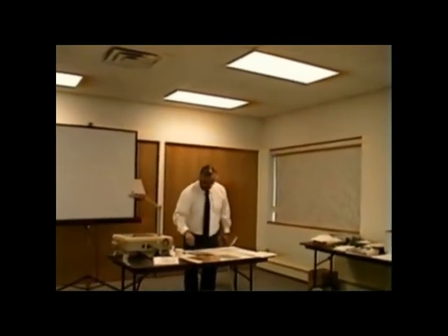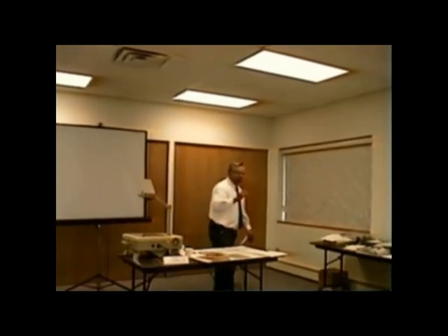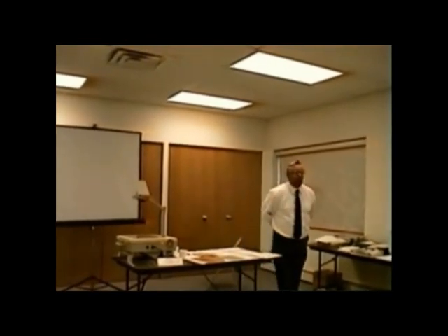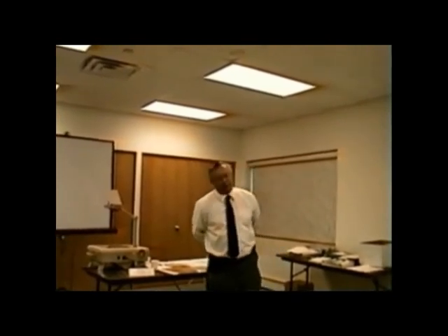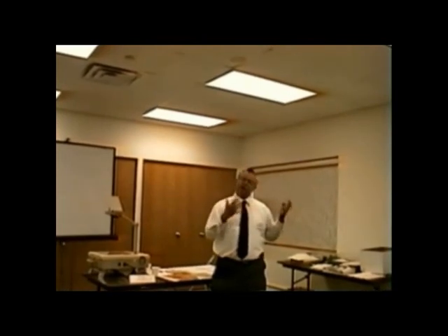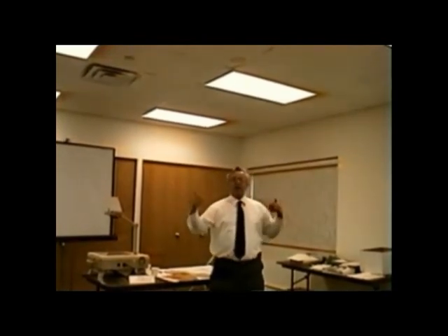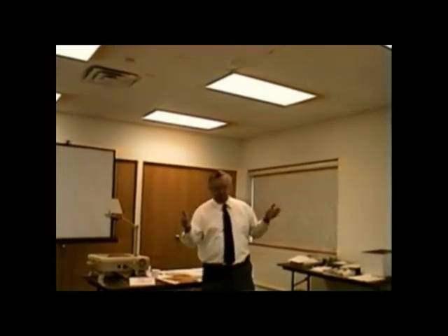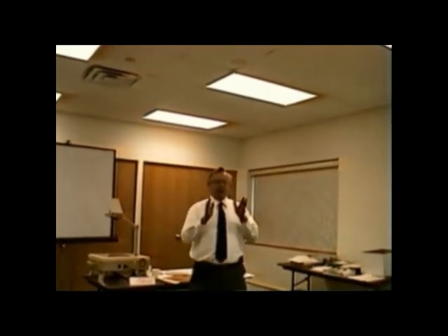When we talk about ESP, we gave you the specifications. We said we got 0.12 and 0.5. Well, 0.12 is for a furnace without air conditioning. So if you have no coil and just a furnace, the external static pressure to the furnace is only 0.12. Typically, we are servicing with A coils in there, with evaporator coils. So the specification that we're concerned about is 0.5. Let me explain external static pressure to you.